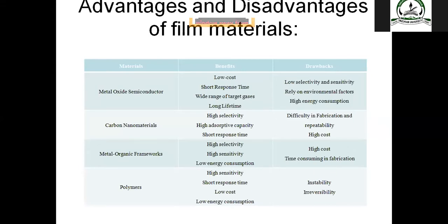So we have to see the site where you can use it. There we can use the optical sensor, where only light passes through. If an electrical signal or current passes through the aviation fuel, the problem is that there may be a fire. A little bit of disturbance takes place, it is highly flammable, it will catch fire, and there may be an explosion. So we have to see the place and what materials we are measuring, and according to that we have to choose the sensor. That is the first thing we have to do.